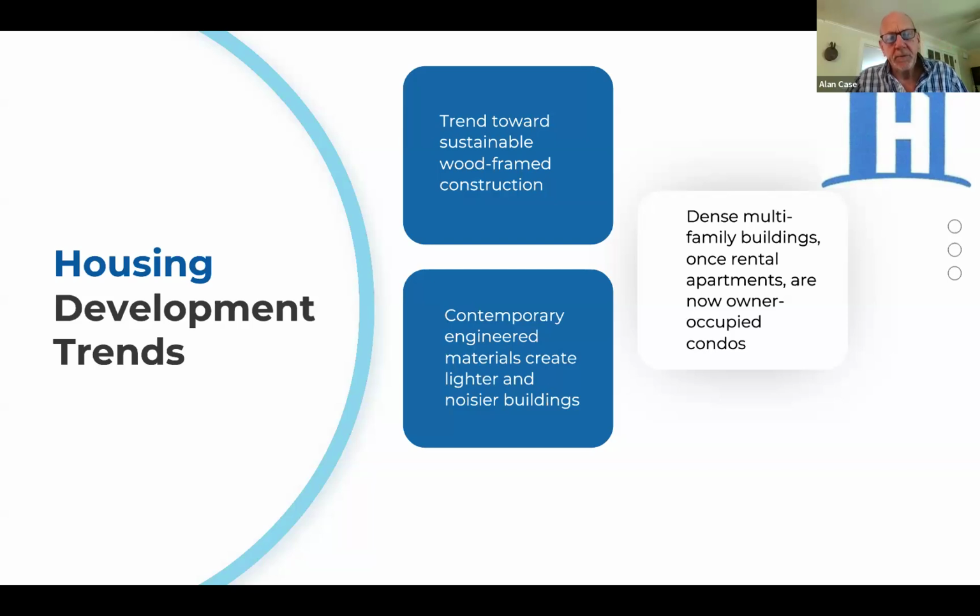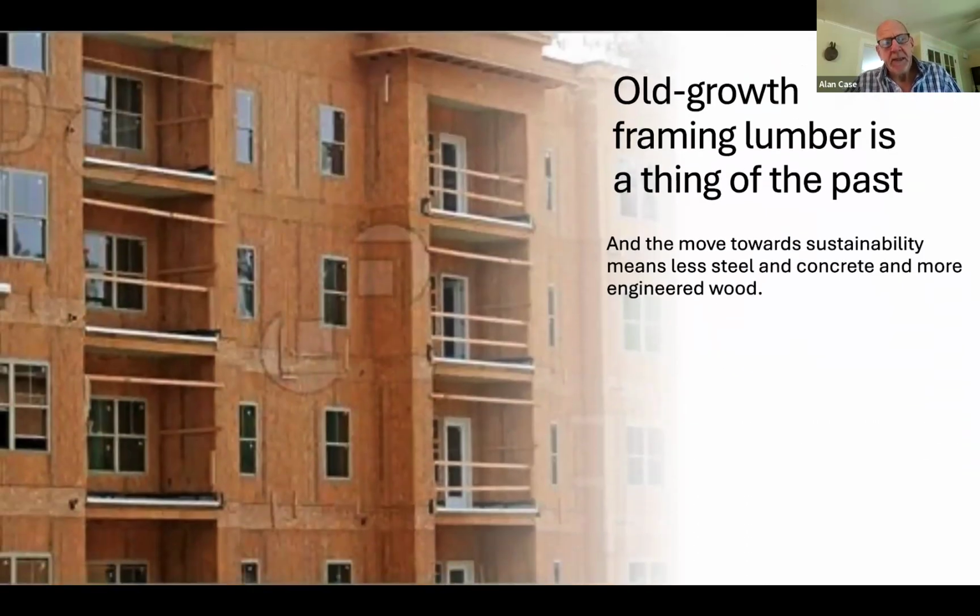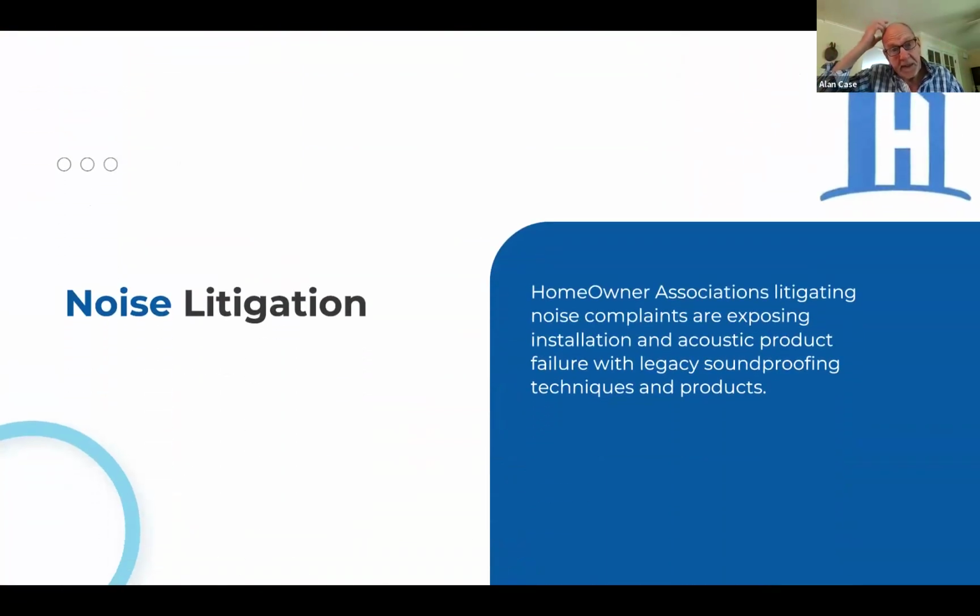All you're required to do on a 12-inch truss is put a single sheet of 3/4-inch subfloor on top, and with the HushFrame in the ceiling below with wood furring, you've obtained your 1-hour fire protection, and you also come out with the highest performing IIC and STC of any product combination in the industry.